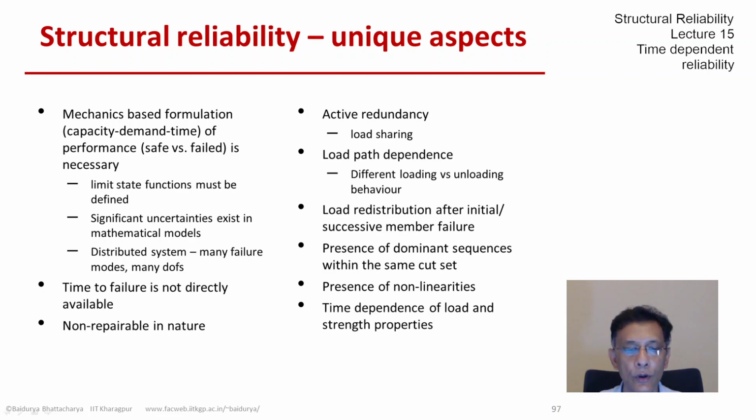And then, as we saw here, load and strength properties can change with time randomly. And finally, there could be statistical dependence among the system properties at different locations distributed throughout the system. So all of this makes structural reliability more interesting, and sometimes more challenging to solve.